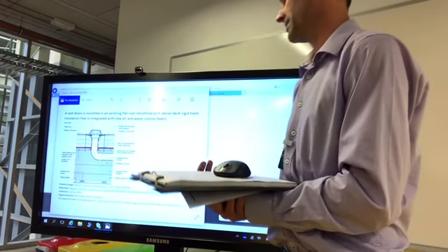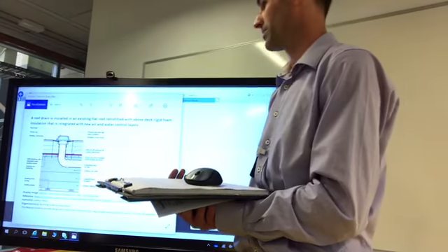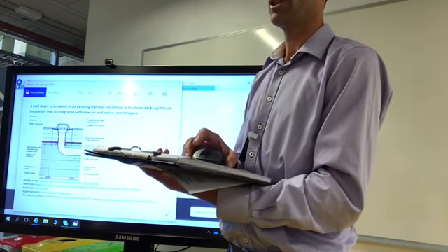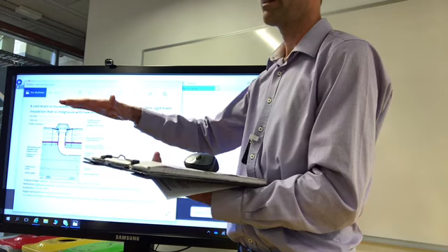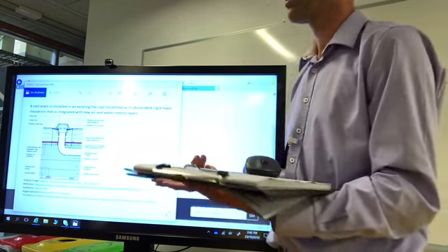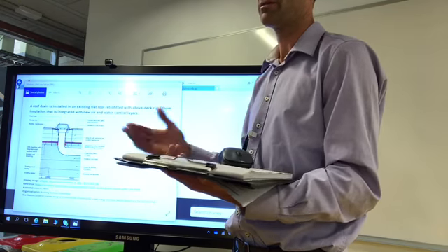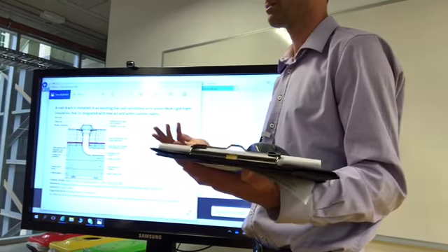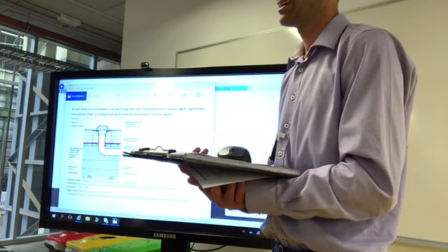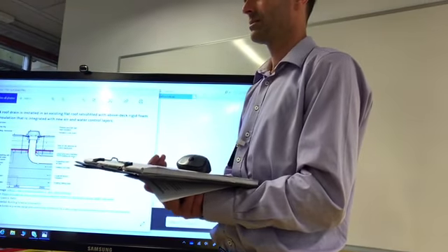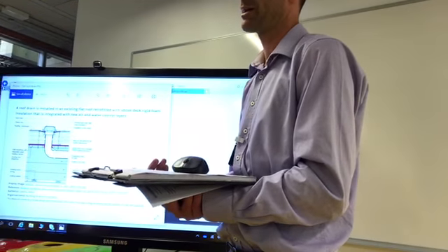Although I guess that's another thing. That's a possibility. You could have a membrane, and then a geotextile fabric layer, and then fake grass on top of that. I mean, that would enable sufficient protection of your membrane, sufficient drainage for any water that makes it through your fake grass. But exactly how you deal with a deck on top, it'd be problematic, I think.